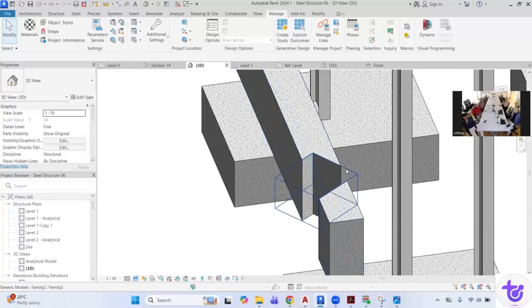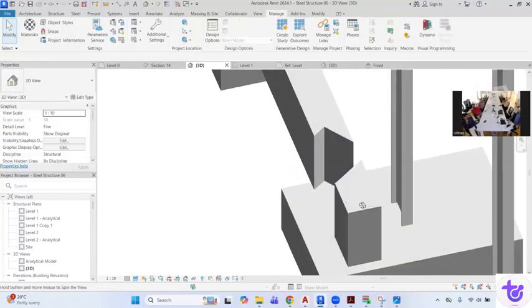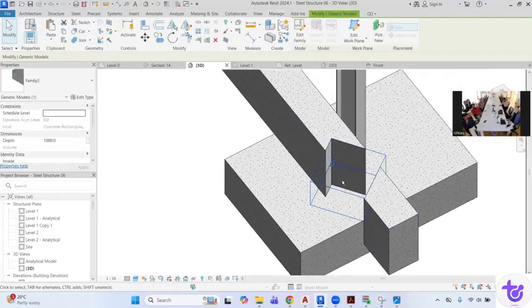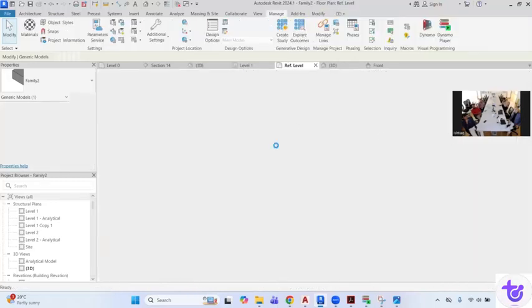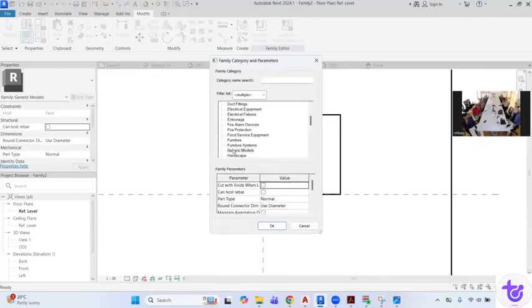Is that okay? Yeah. I think that should work for RC beam especially. And even without getting any warning, you can customize a family, a kind of notch family. And then you can name it. One more thing also, because this is in the generic model category, let me check if I change the type, whether it loses the face-based thing.